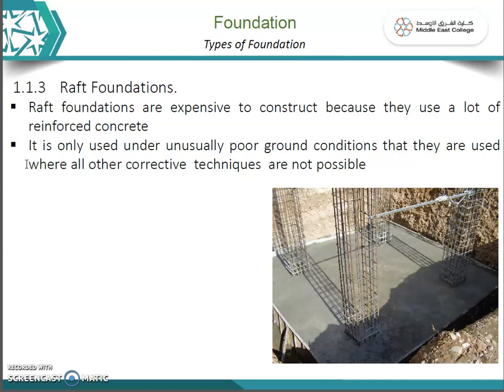Which is used on a lot of reinforced concrete. It is only used under unusually poor ground conditions, where all the corrective techniques are not possible. So other types of foundations are not suitable and there is a chance of uneven settlement, then you may select a raft foundation.